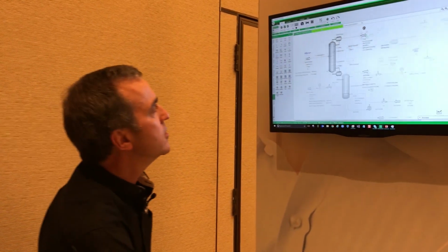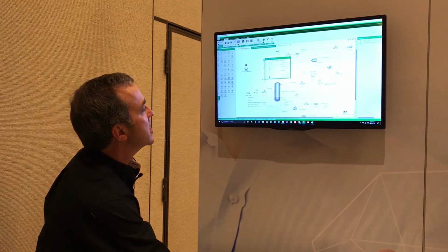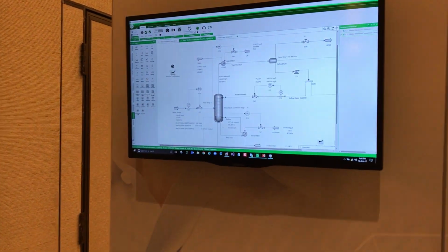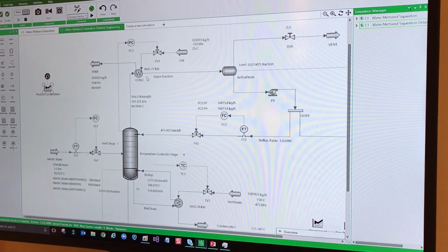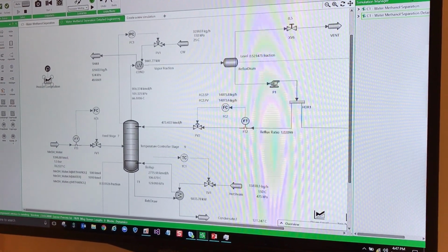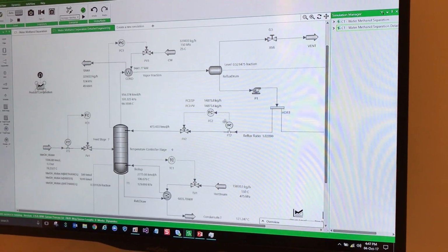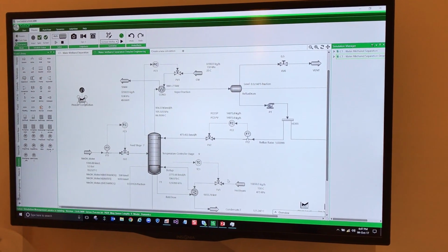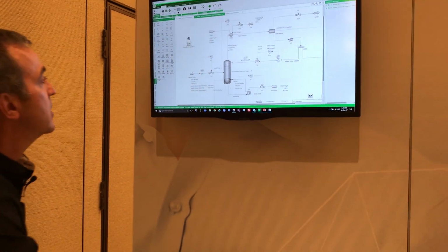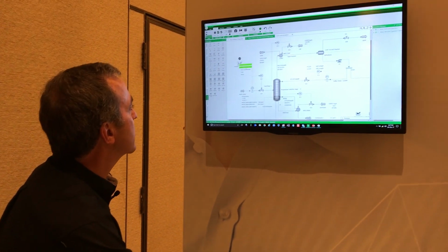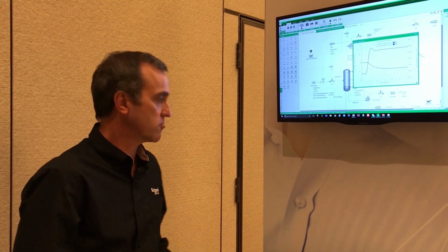During detailed engineering, you can go to a much more sophisticated model. This is the same process, but now I have separate models for the heat exchangers, for the condenser, for the overhead receiver, for the pump. Mechanical engineers can help design, collaborate on the exchanger design and the vessel design. Control engineers can help define the control strategy, where to put the controls, and they can all work together on a single simulation model. Later on, you can run the same simulation model in dynamics and show the transient response of the process and see how the controls work.